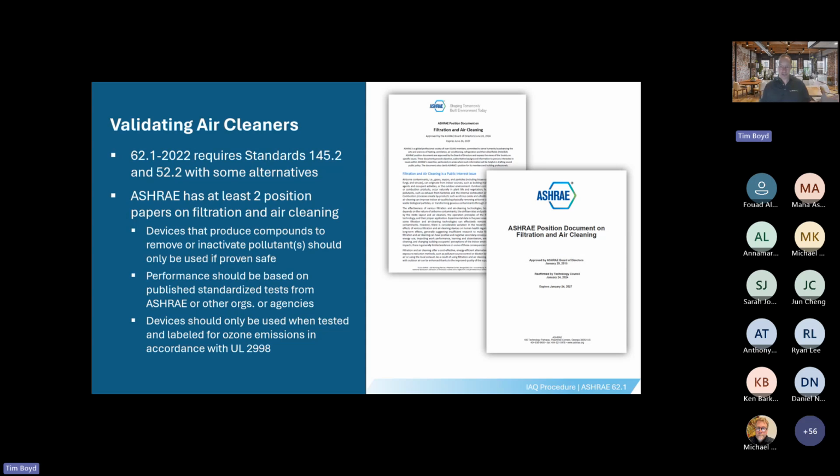So you set up a clean lab, you rate that clean lab, so class 4, class 5. And then as you run the test, if that product is reacting or adding anything into the air, it's going to fail that test. Effectively, with the clean lab requirement, you can go one level above, but you can't go 2 levels above. So if you set it up for a clean lab class 5, the test can gravitate up to a class 6, but it can't go above that to a class 7. That would be a fail.